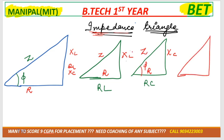And in the case of RLC, in this case we'll have resistor, we'll have XL and XC both. So if XL is greater, then you need to do XL minus XC. If XC is greater, then you need to do XC minus XL. Okay, that depends on which one is greater, and this one would be impedance.